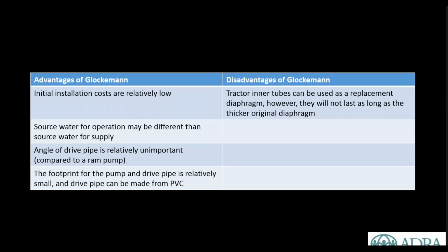The other thing is that, I'm not sure if this is an advantage or a disadvantage, the maximum pressure entering that pump is only 1.8 metres. So if you've got more than 1.8 metre fall between your source and your pump, you would have to put a stand pipe or a vertical open PVC pipe upstream of the pump so that it overflows before the pump gets overpressurized. And the level of the top of that pipe would be 1.8 meters above the pump itself.